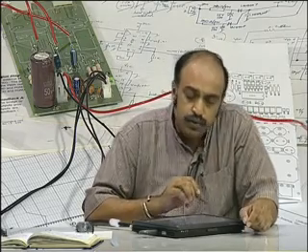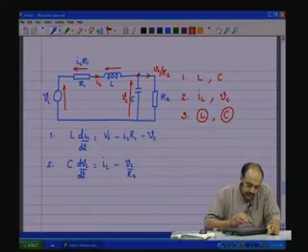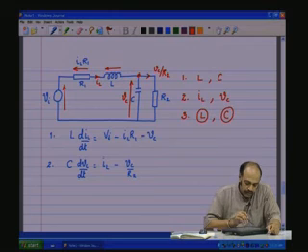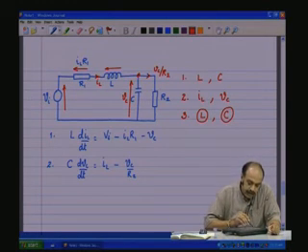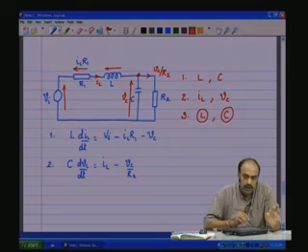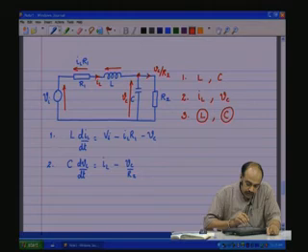And if it is a loop like we see here, just check if all the voltages across the components have been identified. Like for example, in the case of the resistance here, it was not identified, but it will always be expressible in terms of a state variable. So, try to identify that state variable which will decide the voltage and so on.